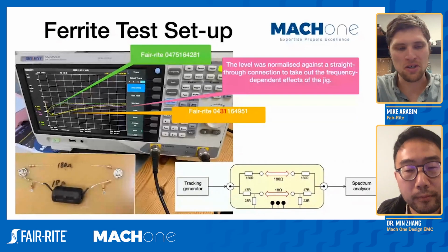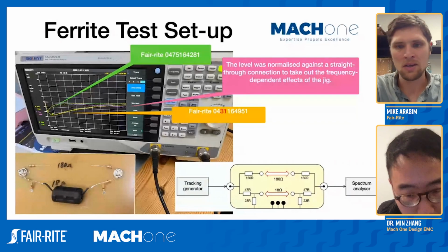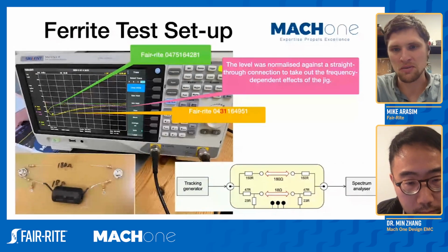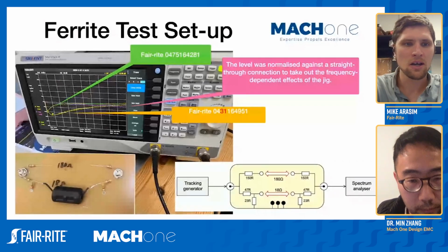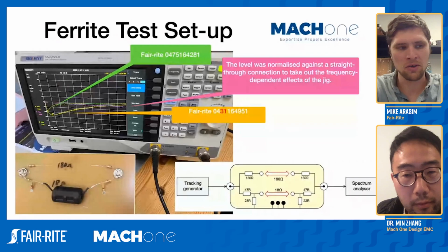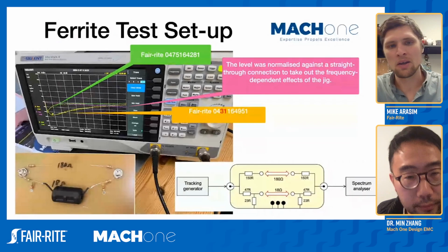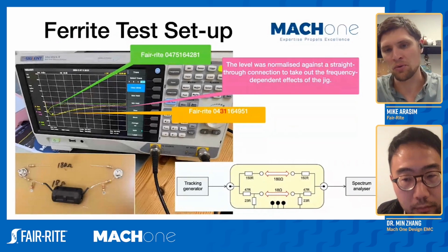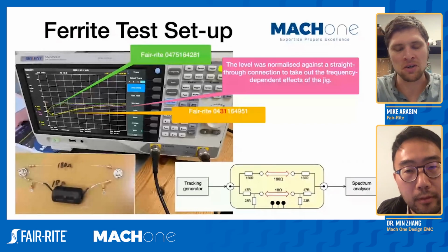So the workhorse of the measurements we make for suppression components is an impedance analyzer. We'll use different analyzers depending on the frequency. Typically, it's an Agilent or Keysight 4990 or 4991. That's a 50 ohm loaded impedance analyzer, just single port. Now, we use a couple of different test fixtures depending on if we're talking about an on-board or an on-cable type component. This is the case here.